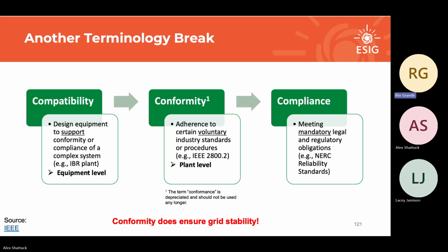Conformity is adherence to voluntary industry standards, right? So you would be conformant with an IEEE standard. Compliance is mandatory. So you're conforming with an IEEE standard, but you would be compliant if it was a NERC standard.